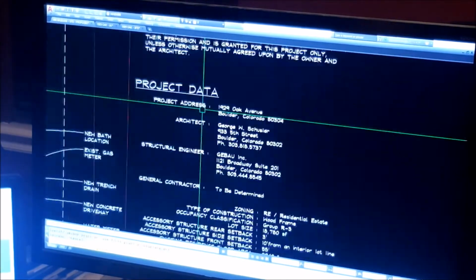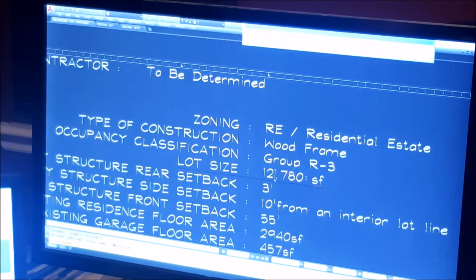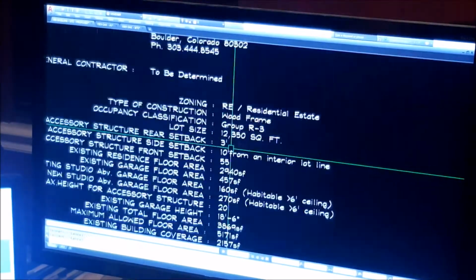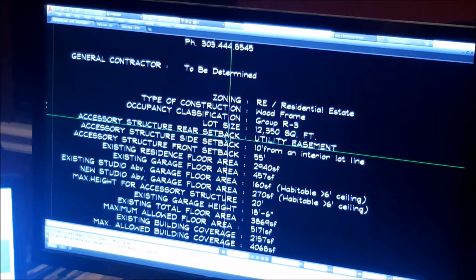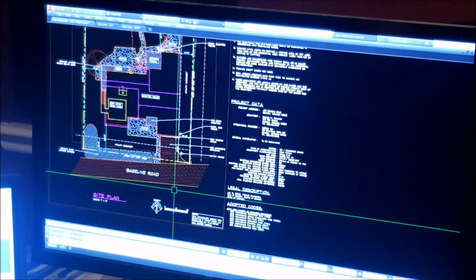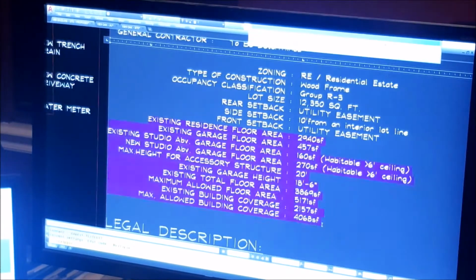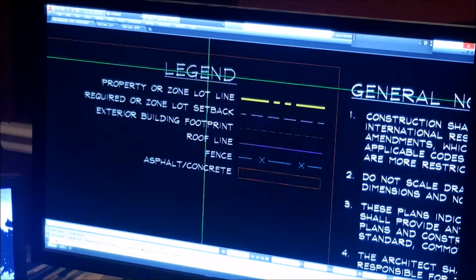And then these notes. These are general notes. I use them under the project for his project. I'm just updating them. Square footages, where the setbacks are. Actually, utility easements, which, there's no other setback label, so I'm just using setback. Utility easement as a setback. That's other stuff he needs to verify, so I just put it in red on my drawing. Here's some white screen that probably is me just getting statistics and data.